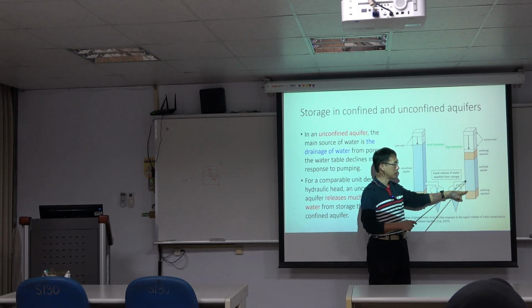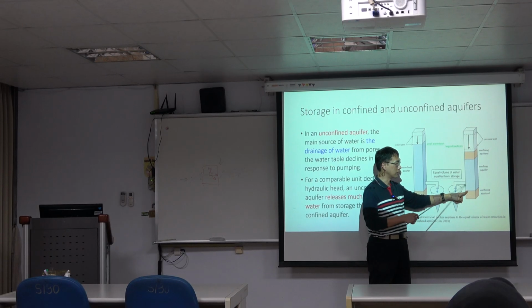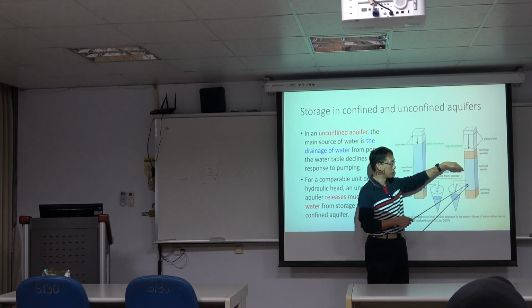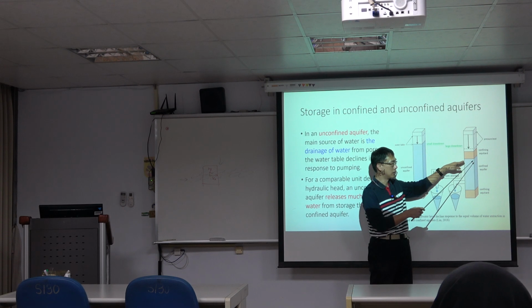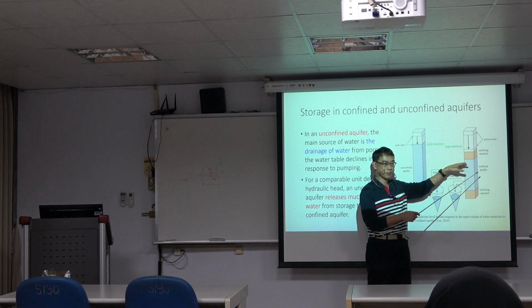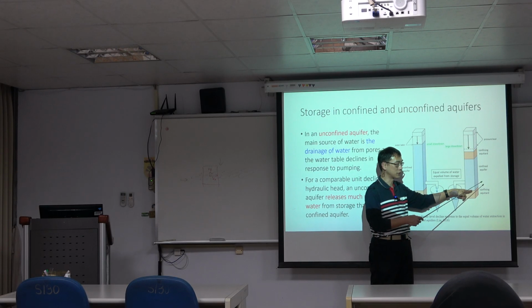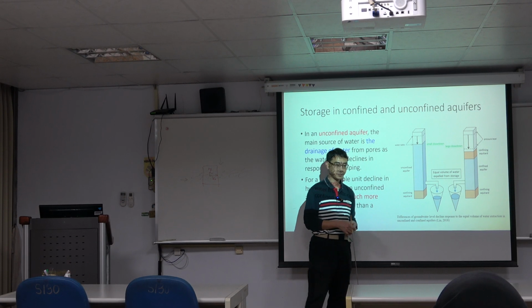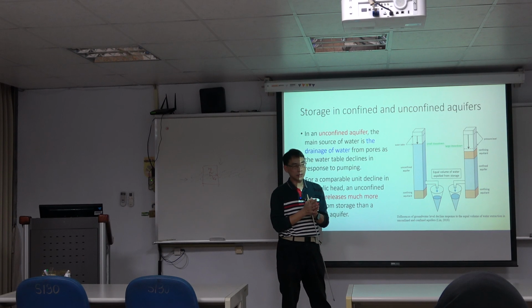And the other part is that originally the water amount in the pore spaces could be 100, but after you take water, they become like 90. 10 is taken out, but how can they be taken out and still be fully saturated? So they will expand. Not that the volume changes, the volume is the same, but the density changes.